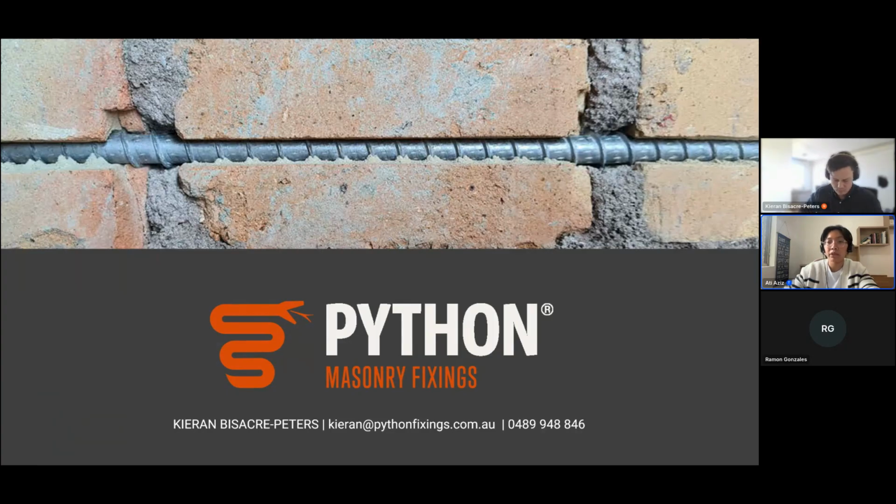Nice. All right, let's do one last question, again from Jesse. Have there been any studies on that coating to ensure it remains in place during installation? Yep, there has indeed. That's a galvanic coating rather than a barrier coating, so it doesn't just rub off on install. In saying that, we've done an extensive study into the durability of the coating system. One of the tests in that study was that anchors were installed and removed numerous times to essentially intentionally damage the coating, and then subjected to extensive salt spray exposure. I can share our durability report covering that and how it performed, and it all performed really well, even with the multiple installs and removals.